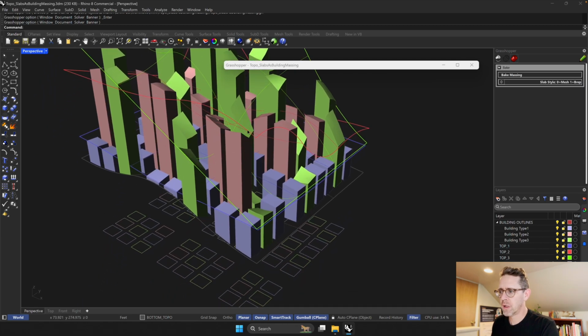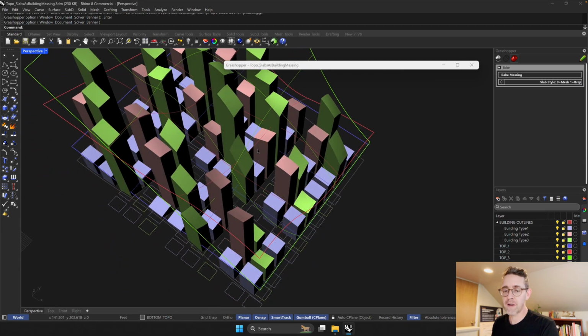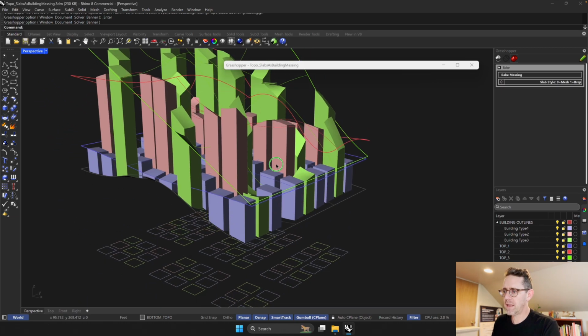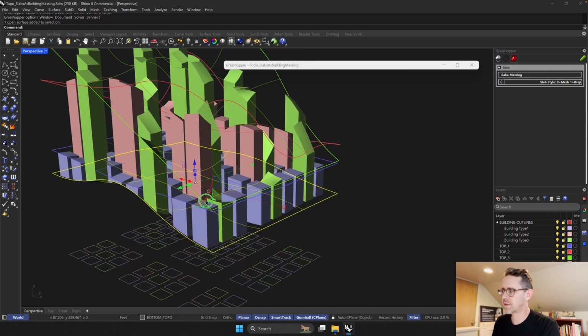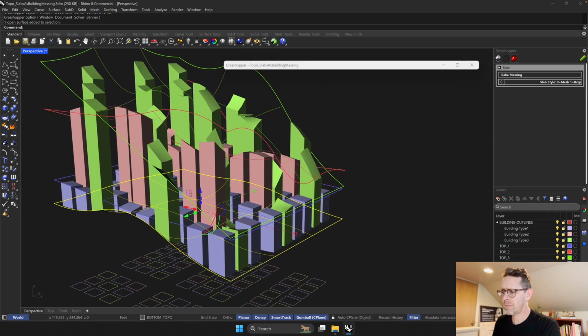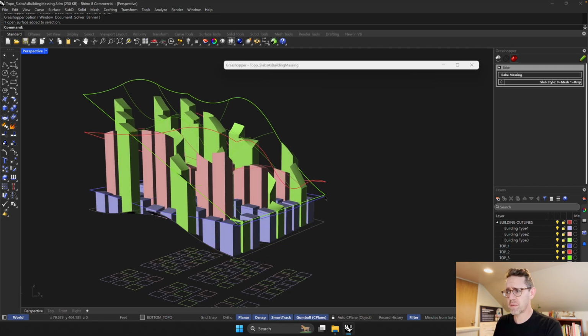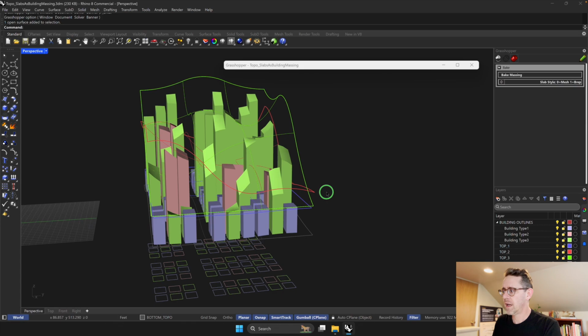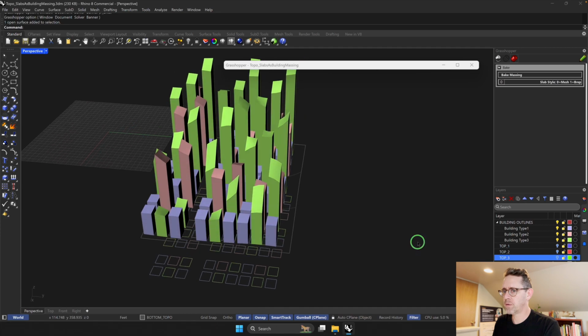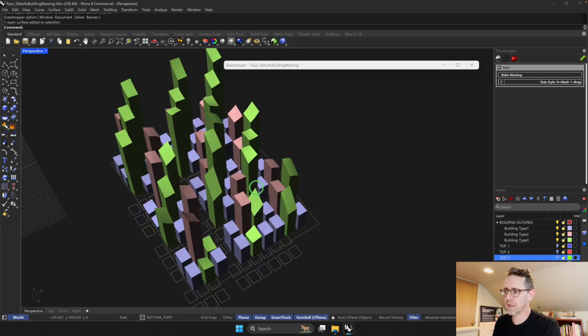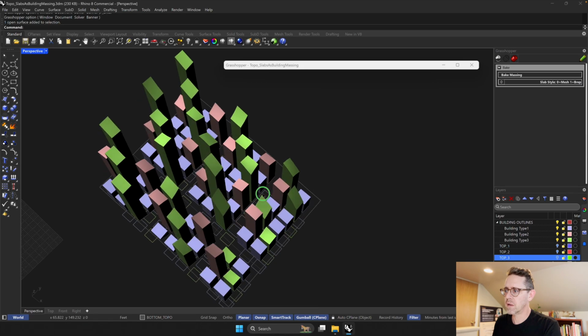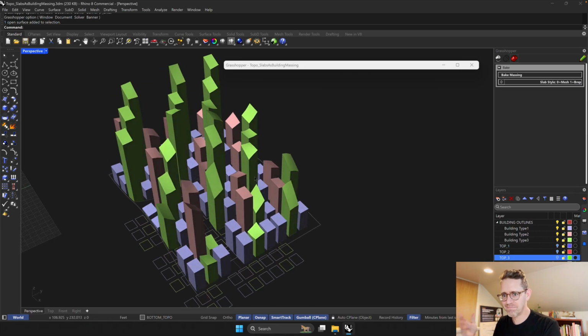Now, the slabs tool gives you the ability to define an area and where that area lands at its top and at its bottom, right? So we are defining a base topography, which is this gray surface. That's our bottom topo. And then we actually think of the tops of the buildings in terms of a kind of topography. And the neat thing about that is that, like, if we turn these on, off, we get this beautiful continuity between building types, and we can create a little bit more light coming in, etc.